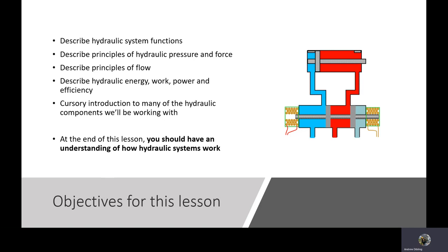In this diagram here, you can see that there is a linear actuator going back and forth. The red indicates a high pressure, the blue a low pressure, and the light green no activity at all. And as you can see, there are two ports, one in the back side of this cylinder, one in the front side of this cylinder. One drives it one way when high pressure fluid is applied, and the other forces it the other way.